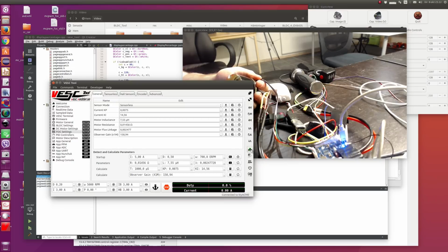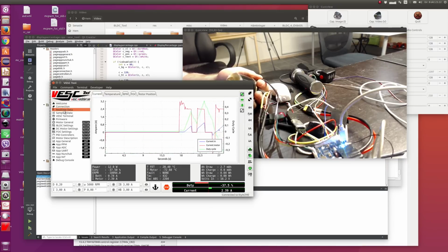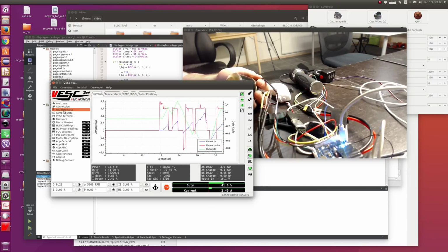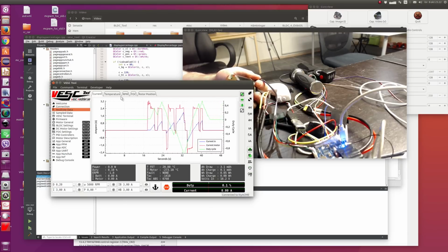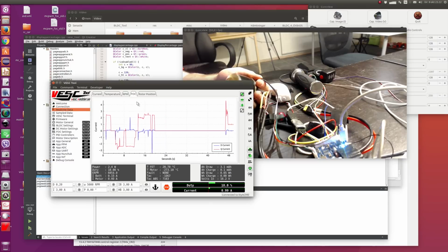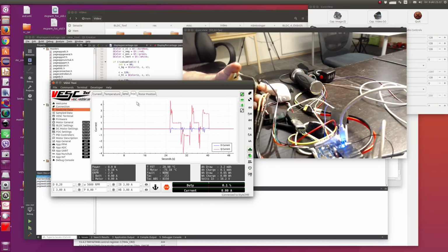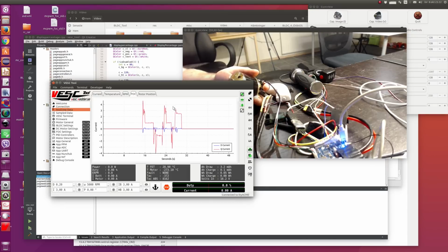Switch on keyboard control in real-time data. You can go to real-time data tab, and then I can use the arrow keys to run the motor as before. I also have added FOC tab to real-time data, where you can see the D and Q axis current when running the motor, which can be convenient for tuning the controller a bit.